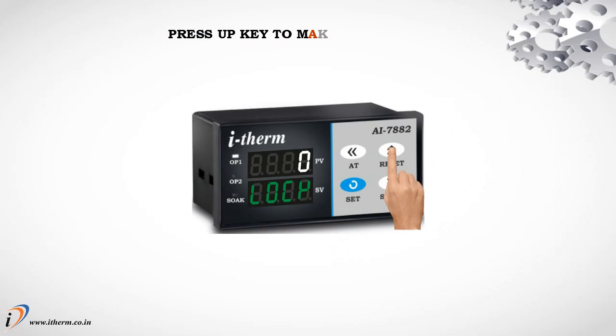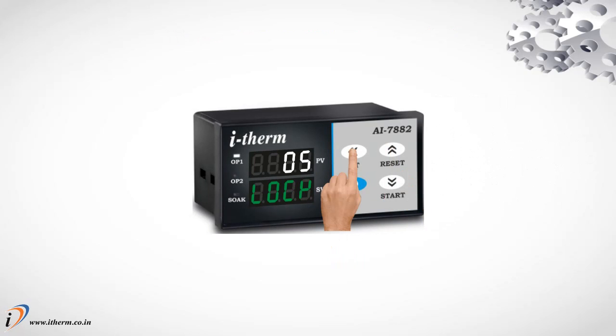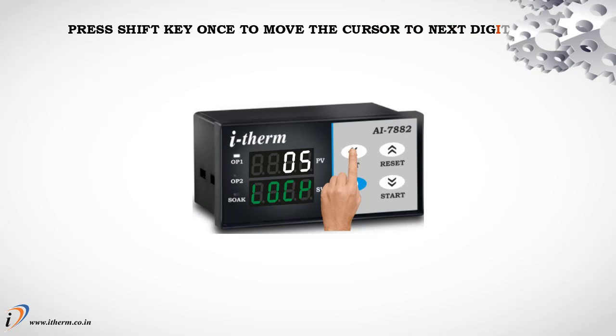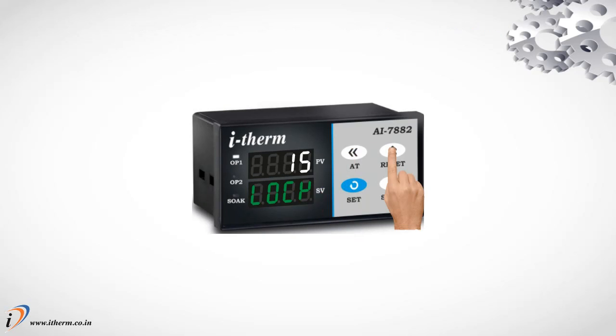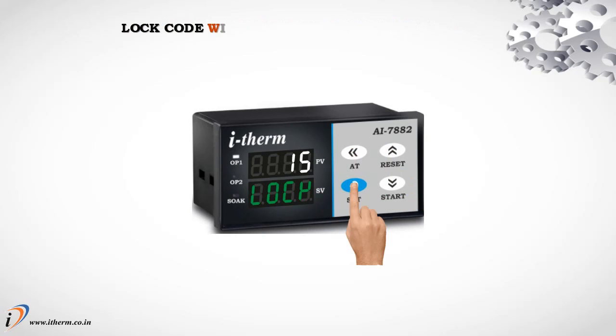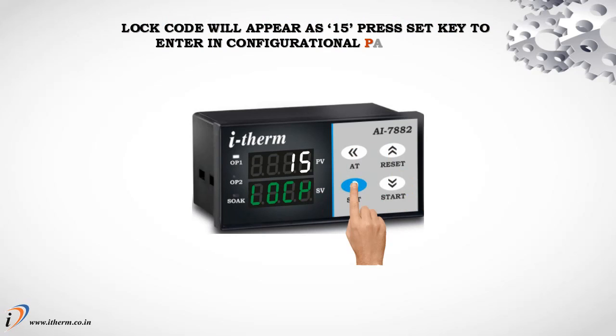Press the Up key to make the unit digit 5. Press the Shift key once to move the cursor to the next digit. Press the Up key to make the unit digit 1. The lock code will appear as 15. Press the Set key to enter configurational parameters.